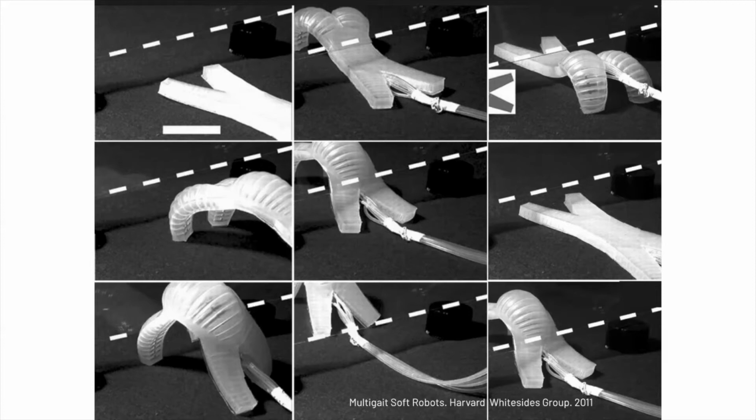You cast silicone into this multi-layer structure, and there are empty chambers, and you can actuate the 4 chambers in a predefined sequence. As a result of the actuation, those 4-limb robots will crawl, and they have different modes of crawling. Some keep a slightly lower body to travel through narrower spaces, and some can lift up their entire body and walk much faster if there are no physical constraints.